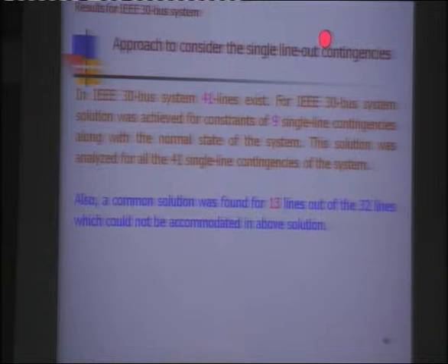because those three lines were creating an additional resistance and reactance in the line, and the calculation of settings was based on the whole system in operation. Now three lines have gone out, so the protection quality is degraded. This is known as contingency, single line contingency.